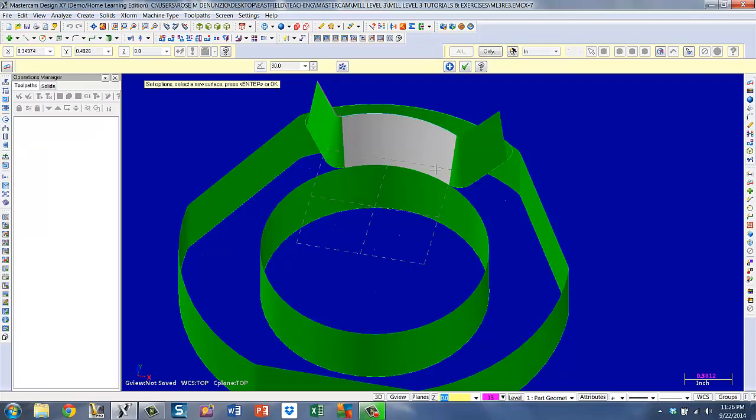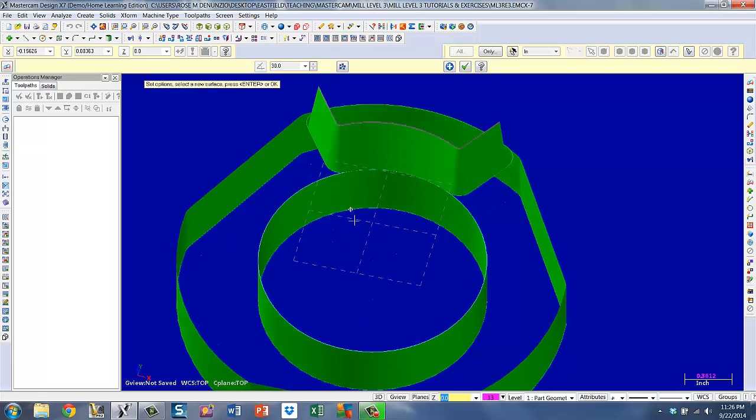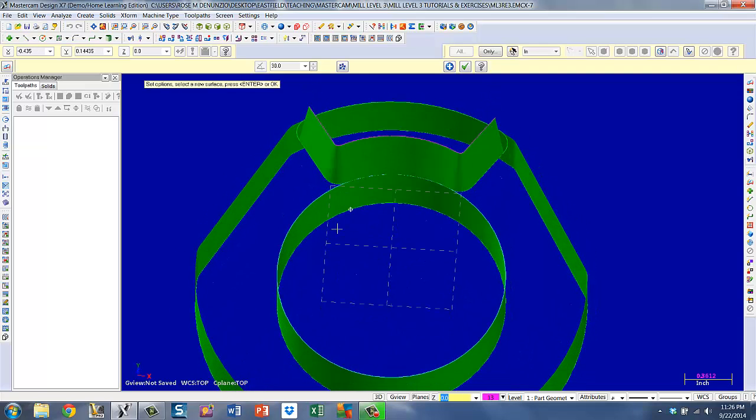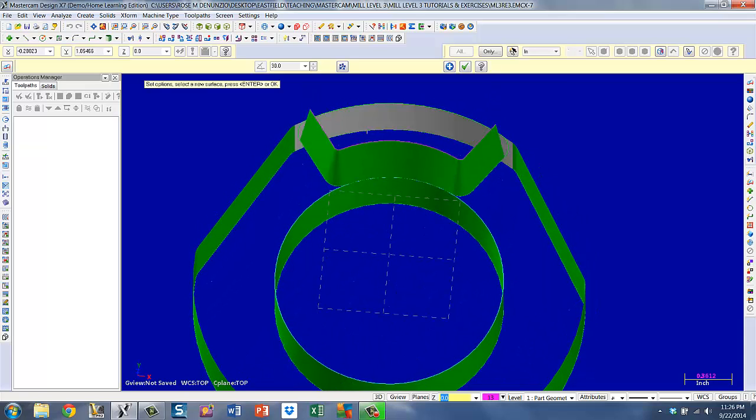Make sure you don't forget the fillets, otherwise when you go to chain everything, there will be breaks in your chain. It'll drive you crazy. It's also part of the reason I change colors when I'm doing the edge surface, but so far it looks like I've got edges on all of those. Now I'll do the center. We're still in the command. There's an edge there. Now if I compress my middle mouse button, I can pivot. Pick that edge, free mouse up and click it.